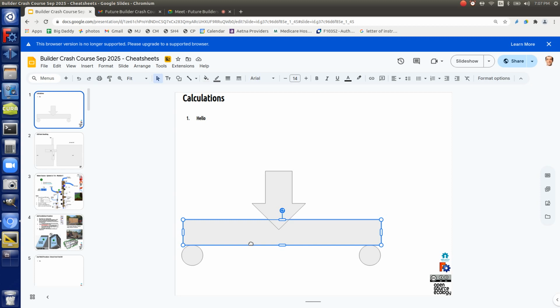But it does not work for extending this thing because you get into that bending stuff. So here, yes, you can double up to a certain point. But at the limit of infinity, it will break upon its own weight. It's non-linear in terms of length. That's why the 32-foot trusses that I'm talking to you about are a great accomplishment. We have a 32-foot span in the current workshop, very expensive. The longer you get, it becomes exponentially hard to keep them from deflecting in the middle.